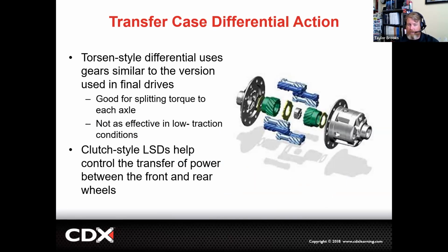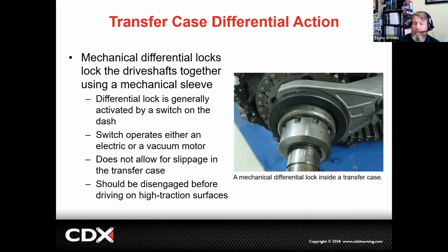We can also have a limited slip style clutch, which is going to have friction-lined plates that again will bind on themselves and allow for some slippage, but then also allow for traction at the same point. Transfer cases, if they are manually shifted, are not going to be synchronized. We are going to move the shift fork manually with a lever or with a rod, and that will engage or disengage the transfer case from two-high to four-low, or even into neutral.